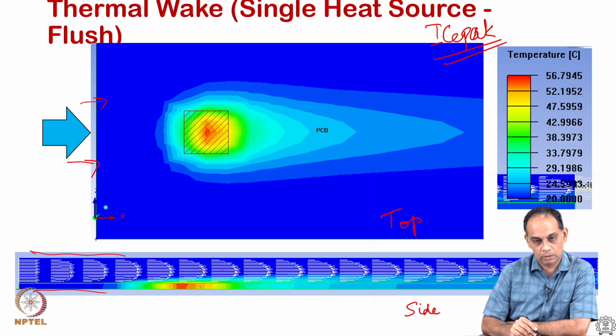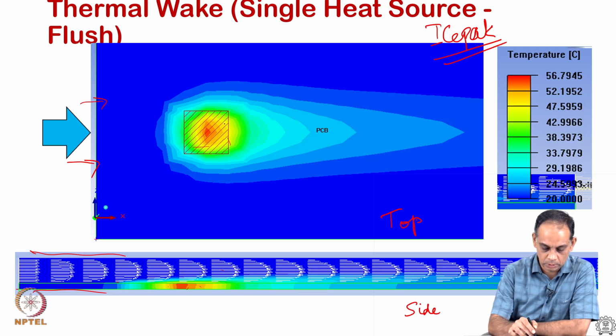Most situations warrant you to have the heat source protruding out, but in the case of voltage regulators, inductors, the FETs, the field effect transistors, the heat sources or the pads are actually on the PCB itself and they need to be cooled. So, let us assume such a situation where there is a heat source, a small pad that is inserted in the PCB and I am flowing air and the PCB is slightly conductive.